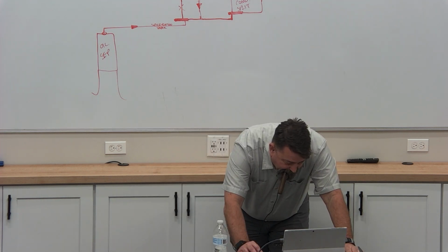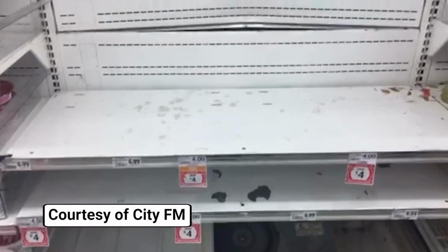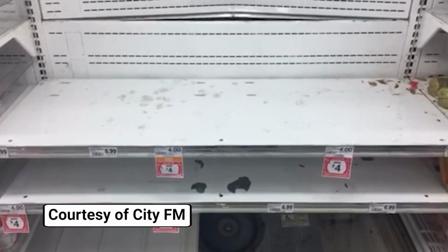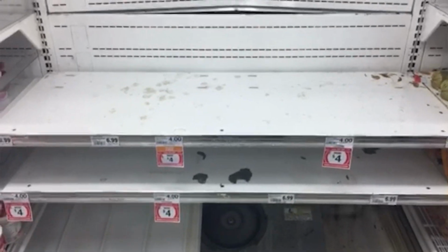Got a little video for you guys. The question is, why is this case having condensation issues? All right, we got water in the canopy. First thing is this ductwork on the bottom. Our deck pan is not installed correct. Notice our deck pan is too low. See that gap? It's supposed to be level with the bottom of this here. Forces the air to be sucked through the front to help with the curtain.